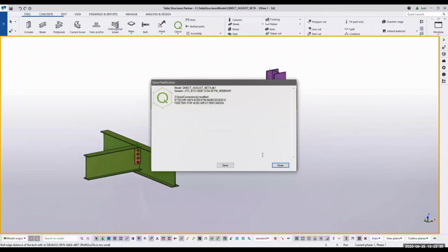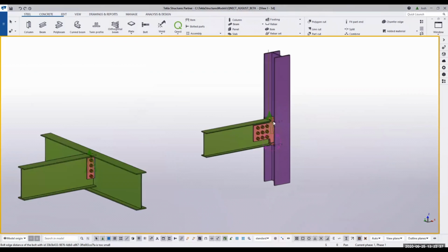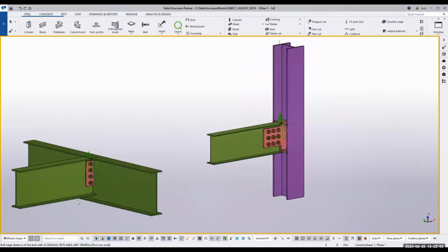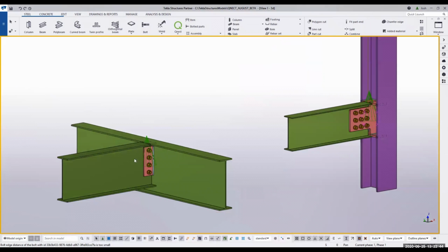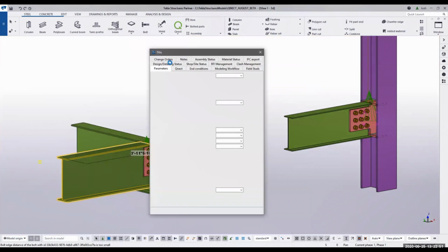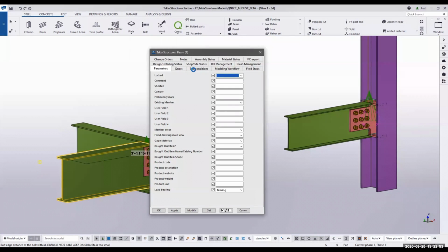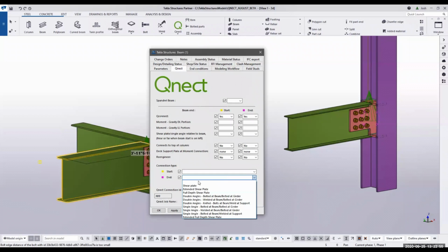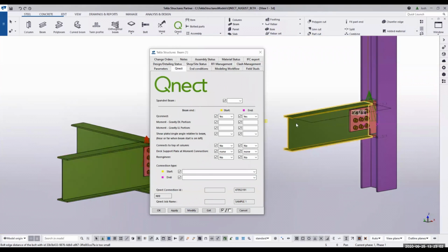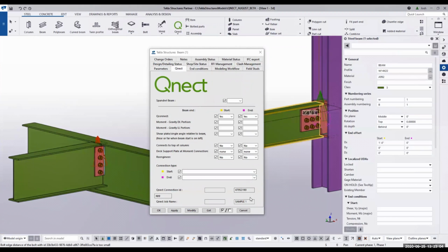So the beam-to-beam, pretty much the same connection. Beam-to-column web, though, has added multiple columns of bolts and a lot thicker plate, larger, probably multi-pass weld. So maybe what we want to do is come in and rerun. So we've looked at this a little bit, and the fabricator decides, you know what, let's go ahead and make this extended shear plate, see if we can get away with removing copes and still have single column of bolts.